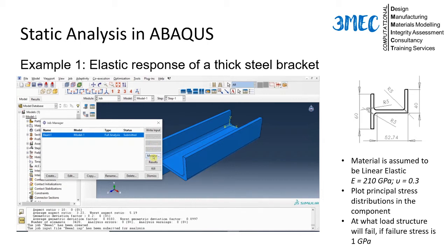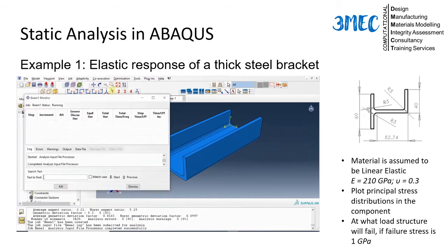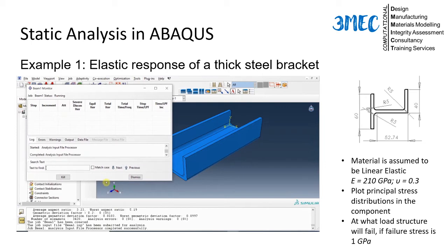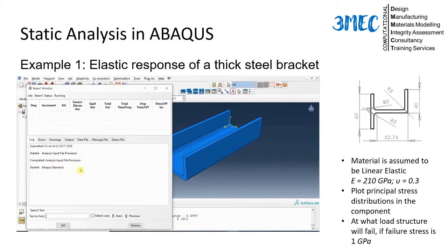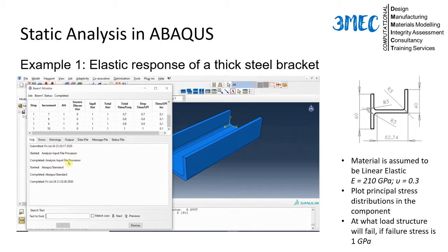As I told you previously, I normally prefer to write an input file and run through command prompt because sometimes CAE crashes and then everything gets really messy, you know. But in this case, it's a small model, so we can live with this. And many people do that for big models as well. It's not like Abaqus CAE is that bad. Just saying. Okay, so now I have run the simulation.